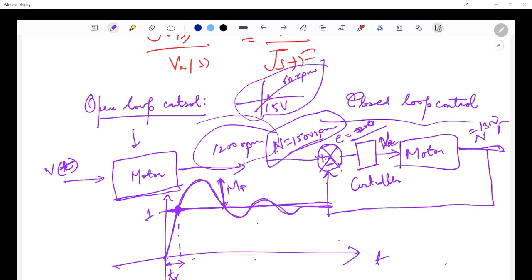Then there is something called settling time. Now for settling time, you might not always be able to achieve the desired value, which is 1. You might be at 0.99999. That does not mean that you haven't settled. You have settled, but there is a very small steady state error. So what I need to do is quantify this as well. So I would say my settling time is measured within a 2% band or a 5% band. Both are ways in which settling time is defined.